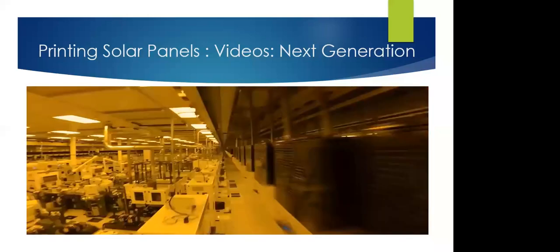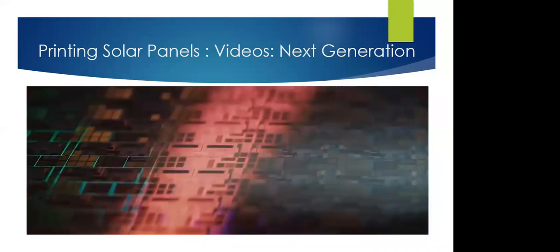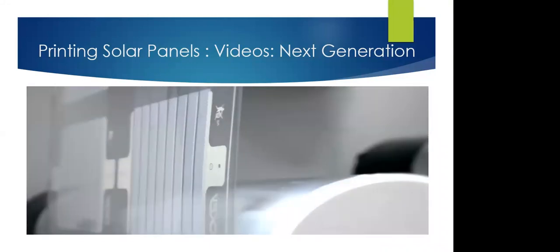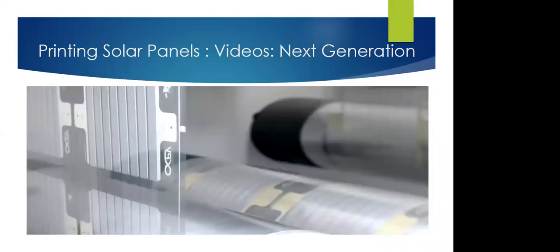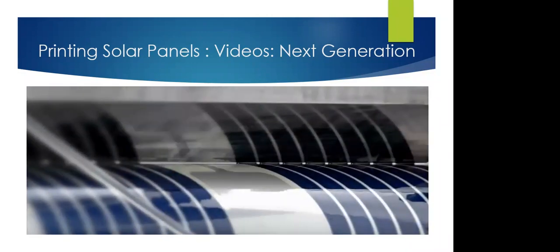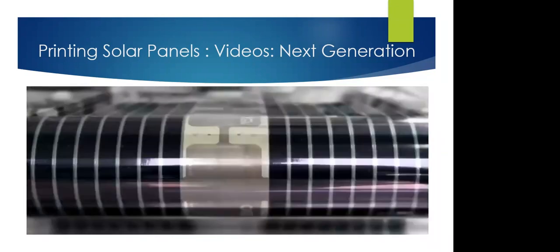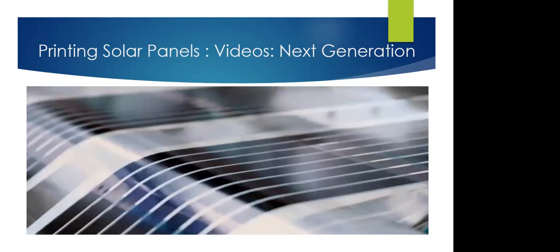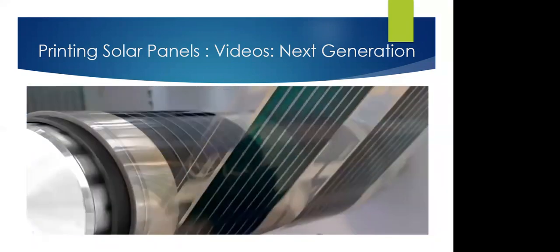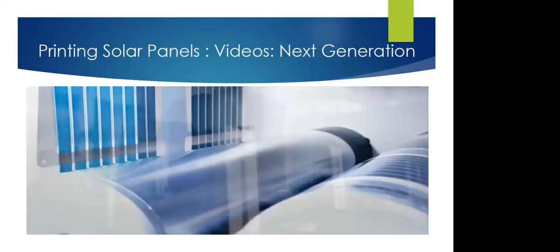Printed PV devices are typically made from many layers of material on a substrate of conductive glass or plastic. Each layer has a function. Semiconductors or sensitizers absorb visible light, and other materials carry electric charge to electrodes. Many types of printed PV devices are being developed. Some feature organic semiconductors, such as polythiophene. Others use light-absorbing dyes, and another subset contains quantum dot solar cells, or nanoparticles that absorb light. The most efficient, though, are the perovskite-based cells.